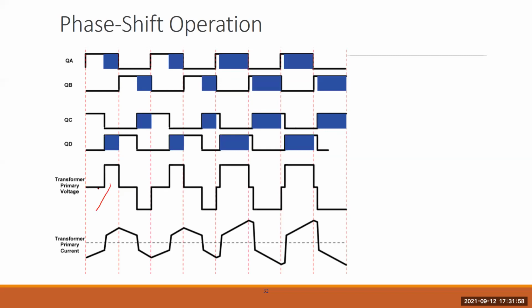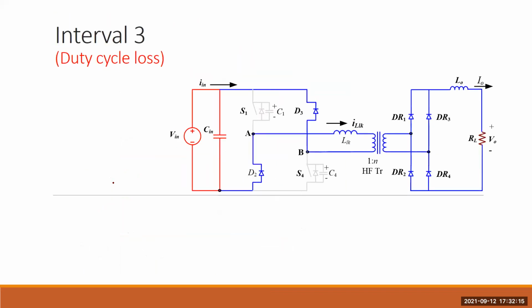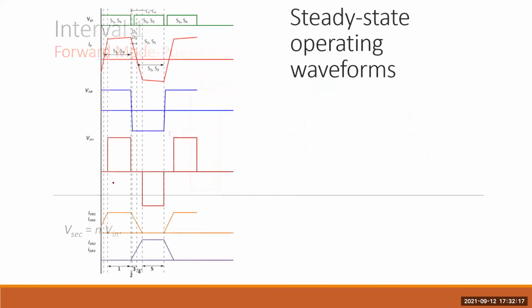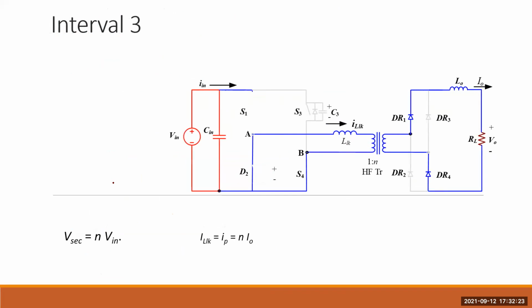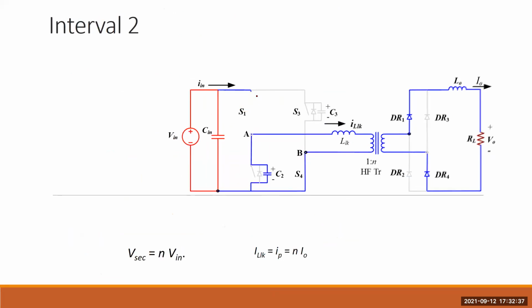this is active timing, and this is basically non-active timing. During this time, circulating current will cause the loss. This time is active timing when the switch pair is on, and this time is not the active timing. This time is basically when the switch and diode are conducting like this. So this is a kind of loss because it is a short circuit. No power flows through the input. So this part is loss.